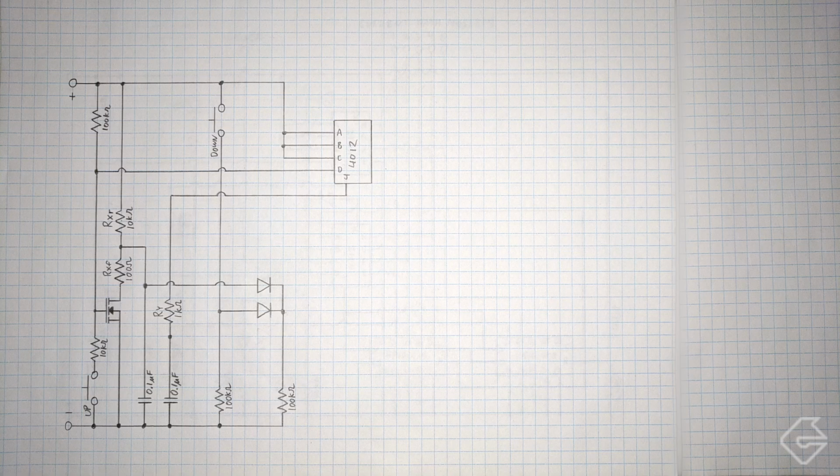So I had to change this resistor to 100 kilo ohms. And when I change that resistor to 100 kilo ohms, that means we're going to get a 0 and a 1 over here. So that part works well. But now the current is so small, these LEDs will never light up. So I couldn't use the light up kind of LEDs in this situation.